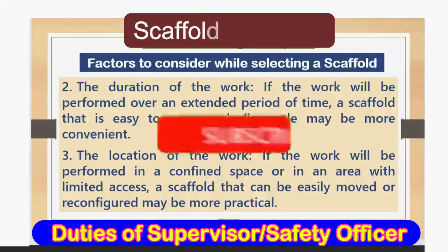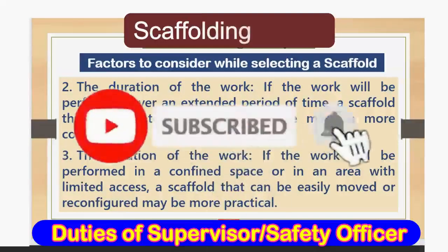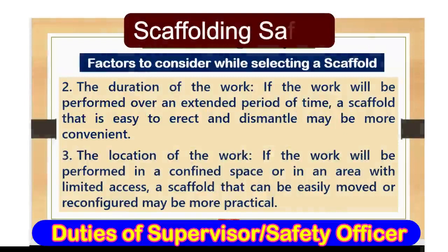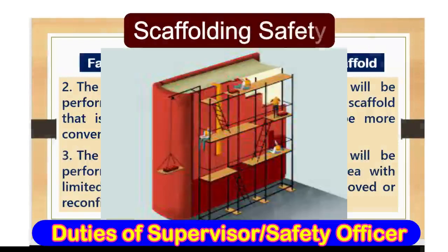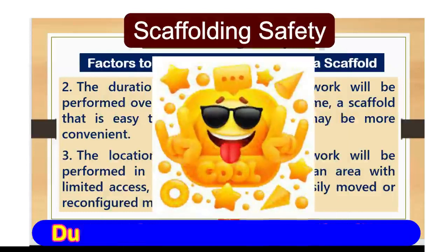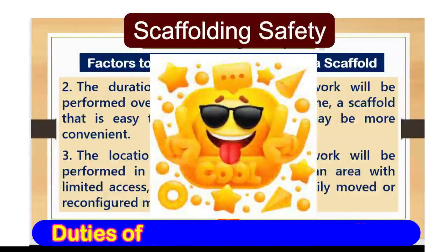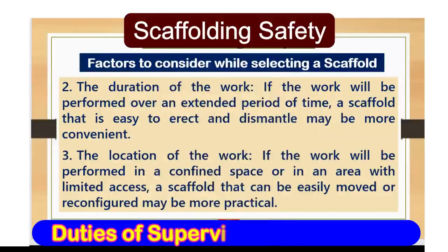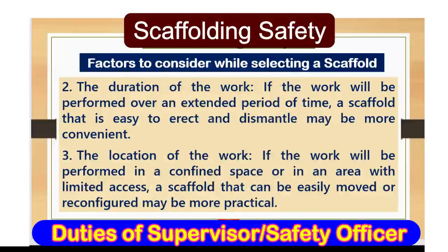Number two, the duration of the work. If the work will be performed over an extended period of time, a scaffold that is easy to erect and dismantle may be more convenient. Number three, the location of the work. If the work will be performed in a confined space or in an area with limited access, a scaffold that can be easily moved or reconfigured may be the more practical or best option.